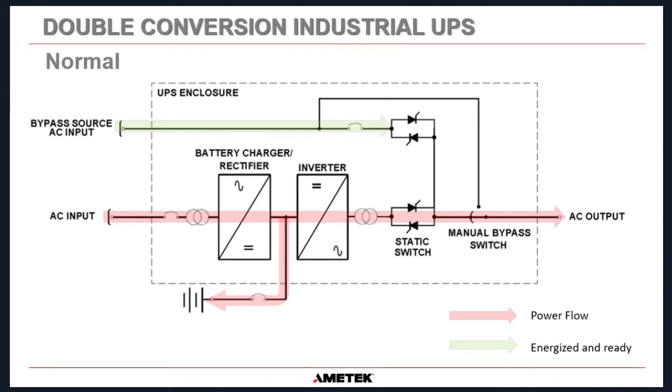So once again, here's the normal power flow for an industrial UPS, and it's very similar to the commercial UPS. The AC input comes in on the left, goes through a battery charger rectifier. The output of that rectifier is connected directly to the batteries. There is no DC to DC converter in between there. So we are charging a 60 cell battery at 135 volts DC. That DC goes into the inverter. The inverter converts the DC back into AC.